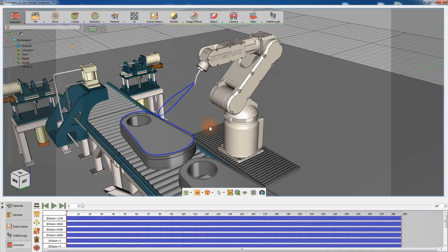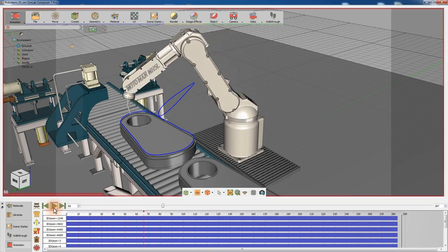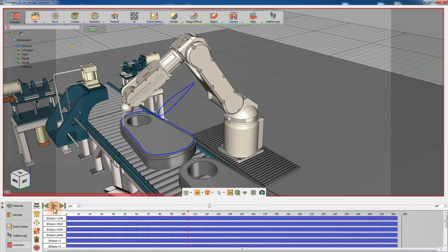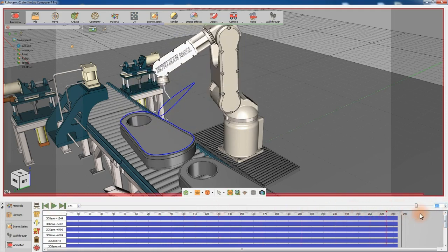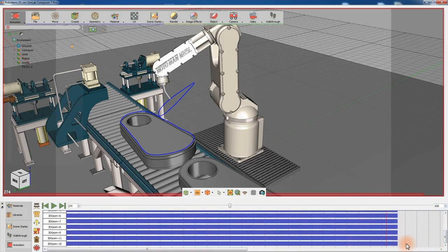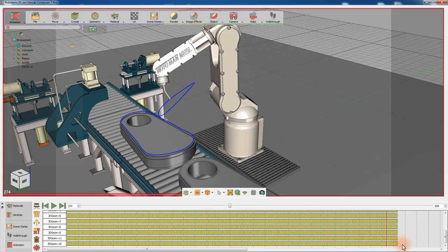The simulation we have created earlier is now baked on frames over time as an animation and can be incorporated in building the scene. Extend the maximum number of frames in the timeline by setting it to a value of around 650. Select all the keyframes that have been created by dragging a marquee box around them. Then press Ctrl and C, then Ctrl and V on your keyboard to duplicate them.